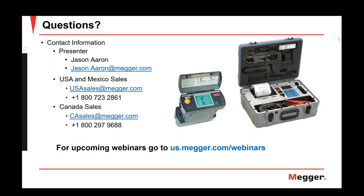You could have false positives or false negatives, where the battery is already dead and the impedance doesn't change, because of the way the chemistry happens. So it's a matter of understanding the battery, understanding the results, and developing your own analysis method. For lead acid batteries, it's more developed, and we have some reference values to analyze the results. That's why it's more applicable to lead acid batteries.